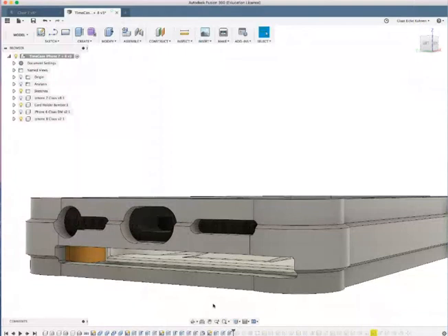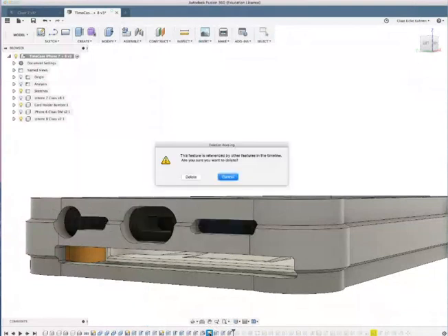One secondary problem is that all these features are totally linked to, for example, the references. That means if I go ahead and select the sketch and by accident delete it, the whole design will break apart, because from the beginning until here the software understands how to rebuild all these features, but now the sketch that is needed to create the following geometry is missing.